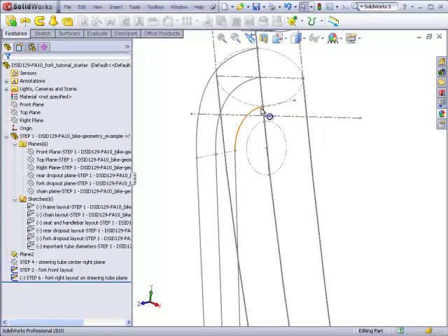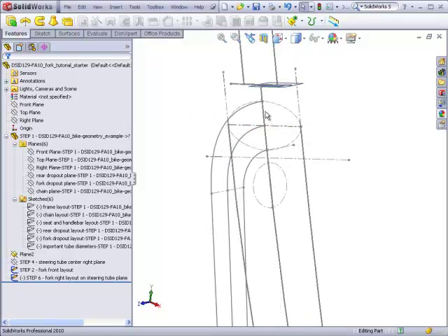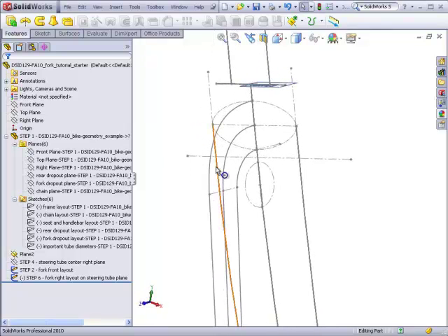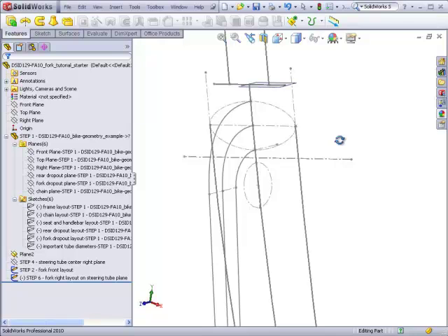And we see how this forms a framework where the important points are coincident with each other between the front and the right layouts. What's going to happen is we're going to repeatedly use these different elements of the layout sketches to create 4 guides.